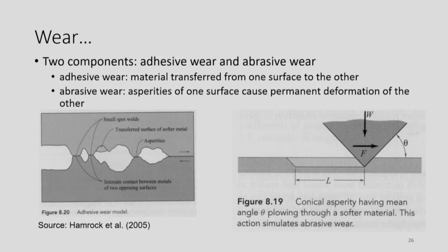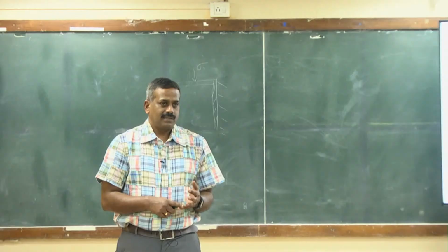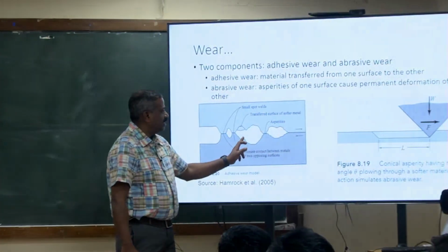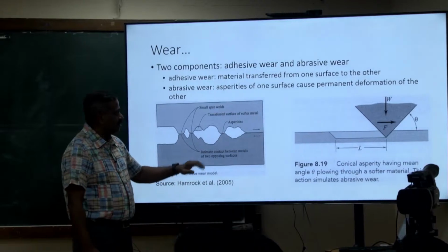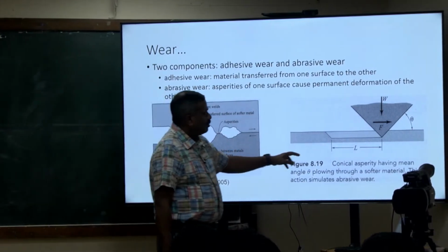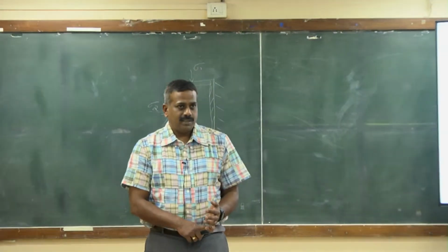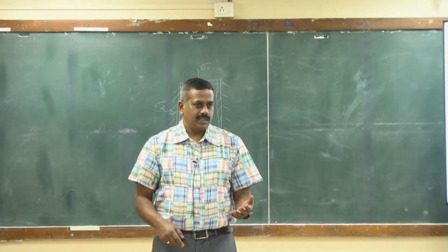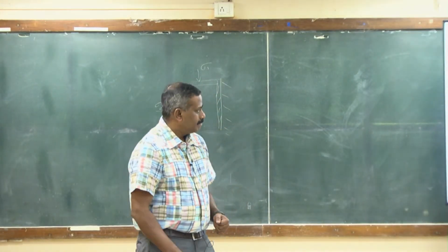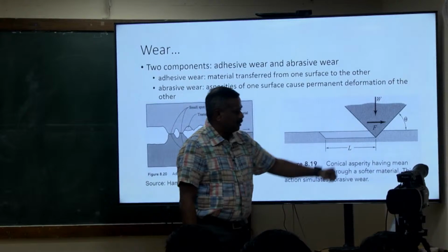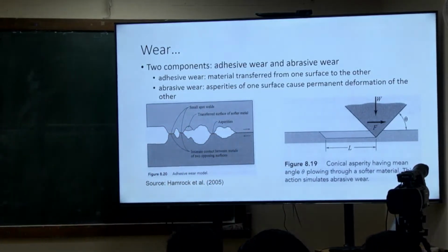So again, it's very similar to what we talked about in friction. There will be multiple asperity contacts between the surfaces, and when one surface is moving over the other surface, there will be stick-slip motion, right? For example, at these asperities, it sticks, and when it's moving here, it's slipping, right? There is no contact between the materials. So again, there are instruments that can calculate the wear. One is, again, we talked about the tribometer, right? Tribology testing is common to get the wear strength of those materials. For compacts, a conical asperity tester is common, mainly for the pharmaceutical industry.